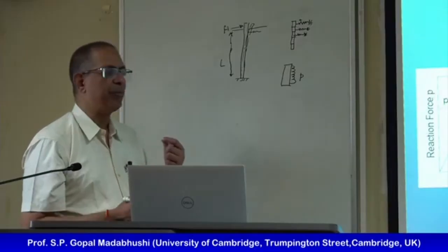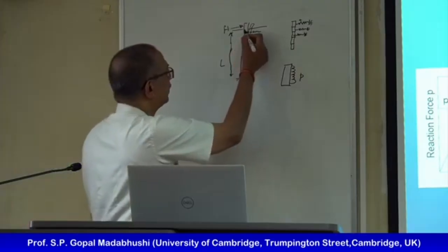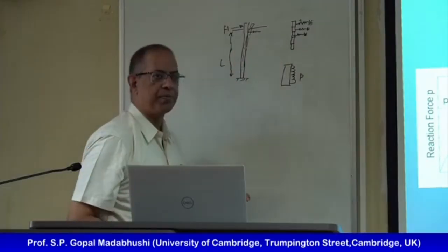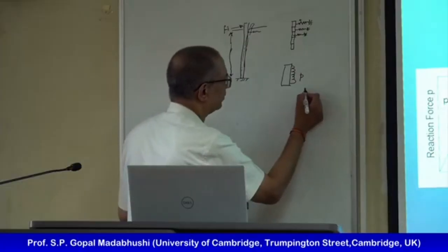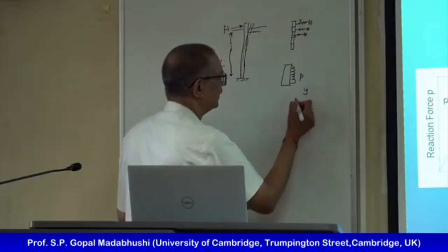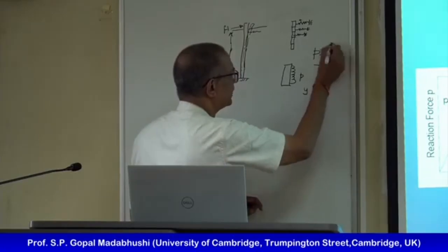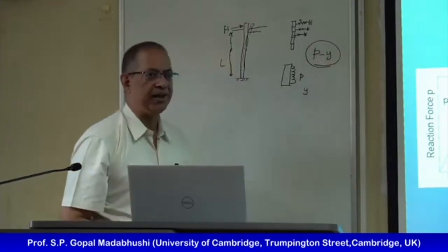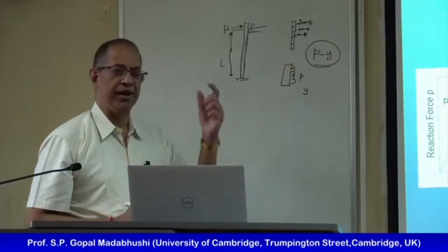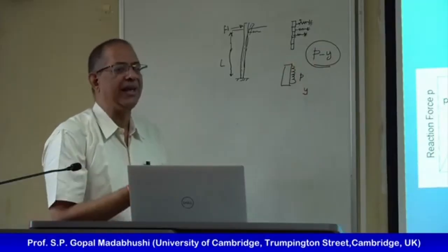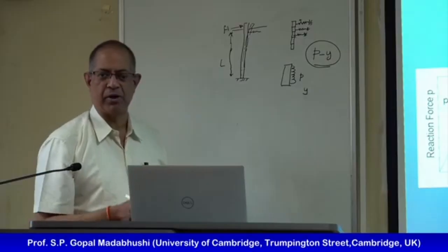So what matters is the relative displacement between the pile and the soil. Okay, so that is called Y. Because we are using symbols P and Y, this is what the so-called PY analysis is. And people like Meyerhof have done this for ages, for laterally loaded piles in clays, sands, Reese, Matlock, and the rest of it.